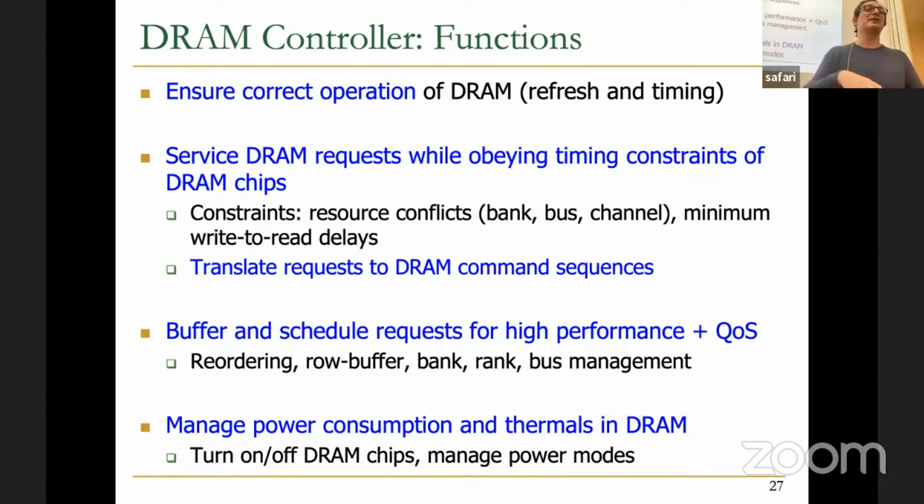But the memory controller can say, oh, I haven't used this rank in a long time. I'm going to turn it off, meaning I'm going to put it in self-refresh mode. There's something called self-refresh mode in DRAM, such that I'm going to tell DRAM, self-refresh this rank. I'm not going to touch you for a while. And when I need that rank again, I'm going to send a signal to that rank saying, get out of the self-refresh mode, I need to access you. So these are some tasks that the memory controller can do so that you can save power. But clearly, this is complicating things, right?